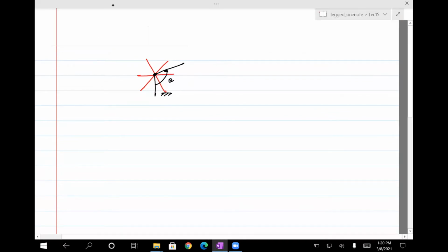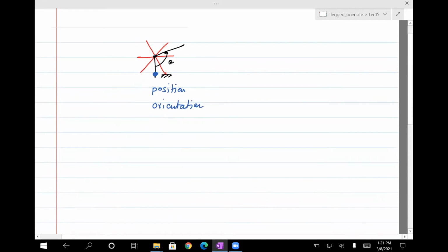So what you do is first you assign a dummy, and I'll just keep the dummy here, just in the projection of the center of the rimless wheel, and then I'll assign it a position, which in this case is just a projection, and I'll set an orientation. Okay, and the way I set the orientation of that dummy is, again, use the same concept of the heading angle or the yaw angle. So if this is psi, I always set that dummy to have its x like this, x, y, and z is pointing out of the plane. So this is how I set the orientation.